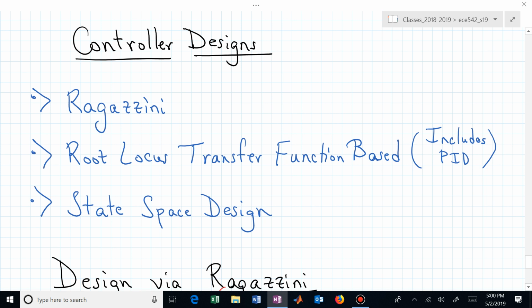And maybe I didn't make it clear last night, but I quickly was showing a challenging system to try to control. How did I come up with those 2 poles and a 0 that I ended up with in that controller? Well, it was actually a state space based design. It was a full order estimator with full state feedback, the controller associated with that, and that now informed my ideas of where to sprinkle poles and zeros.